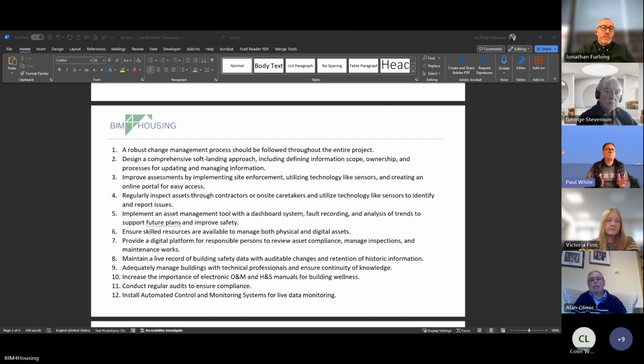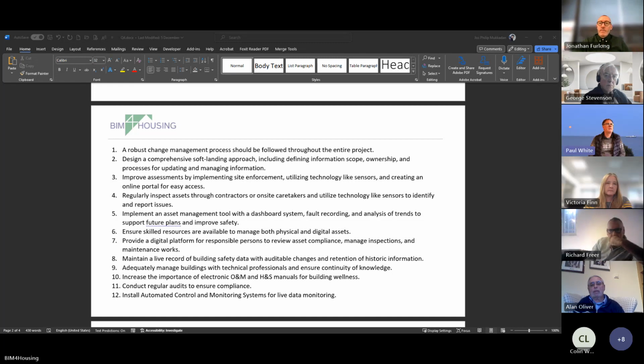One of the other issues with smoke control systems, particularly, is they're passive. Unless you go and test them by setting an alarm off, they don't work, because they're sitting there waiting for an alarm. So you don't know when any of the parts move or do anything else. You said earlier these things don't message somebody. They can, but you have to pay for it at the start. And this is the problem. Everything is available and relatively cheap, but people don't want it.